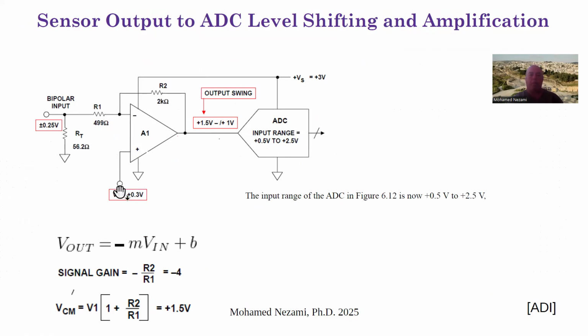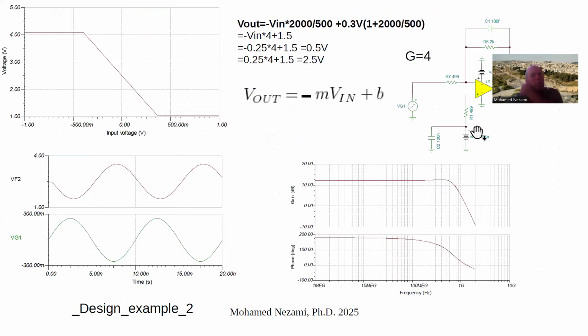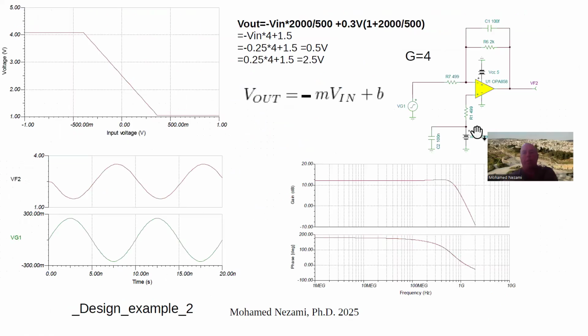It's very important that this reference voltage in here is tied to this voltage, is tied to this voltage, so that if there is any temperature drift in the power supply or any variations, it all tracks so that it all adds up. And so what I did is I put this on the simulator, okay?